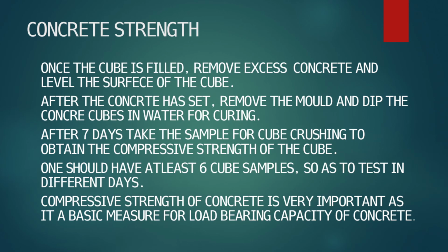Once the concrete has set, you can leave it throughout the night. The following morning, you open up the molds, remove the concrete cubes, and dip them in pure water. You submerge them for curing. Then after 7 days, you take the cubes to a cube crushing machine.